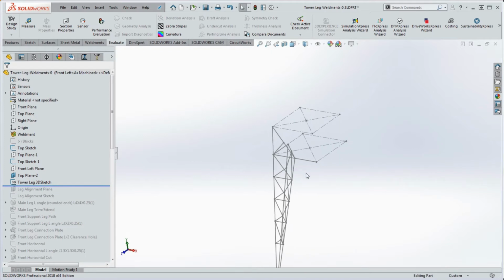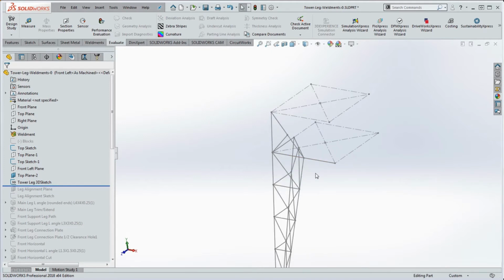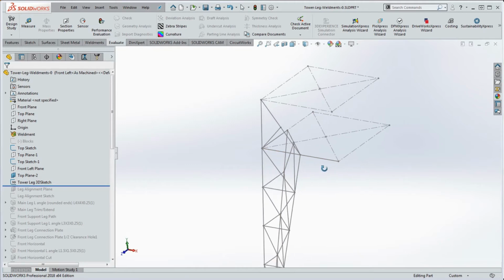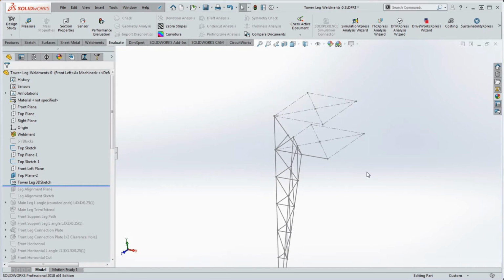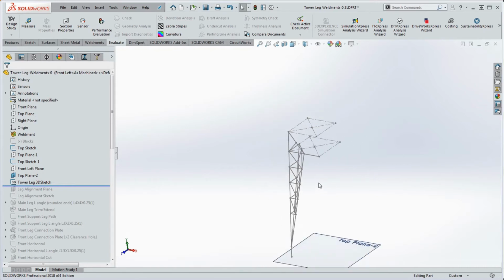Now the 3D sketch, the design sketch here, will drive basic elements of the design, the basic size and shape of it, but for the most part they're not used directly. Used indirectly and sometimes peripherally in order to define our parts. But when you change this design sketch, it changes all the parts that go with that, all the different solid bodies in the part that ultimately is driven by this.